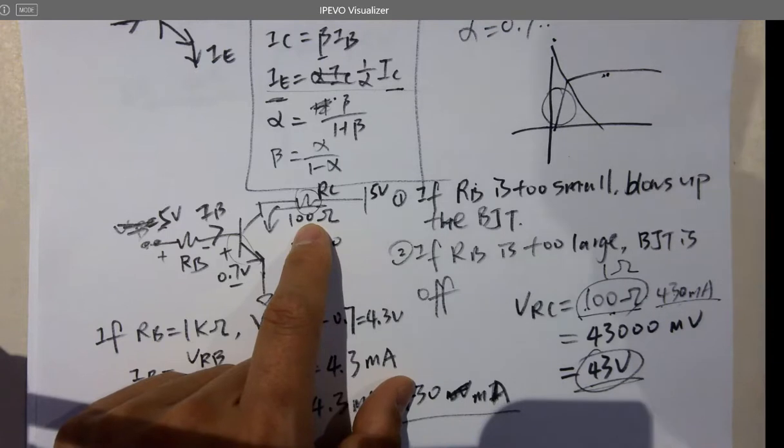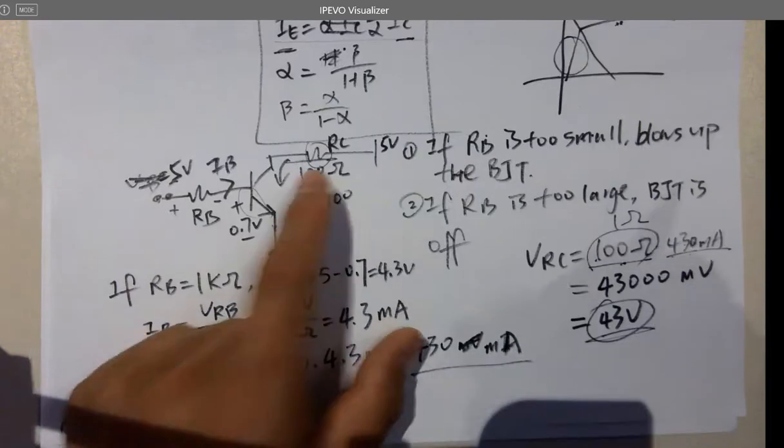So whenever the resistance is low, something like a motor, it is a heavy load. That's why you have to use a motor driver to run all these currents through it, instead of running the high current from the microcontroller, which cannot handle that much current. You have to use a power device to do that. And 100 ohm is also a very heavy load. It's going to draw a lot of current. Just some examples you need to know.